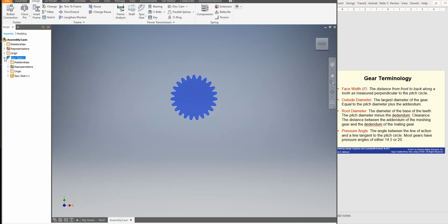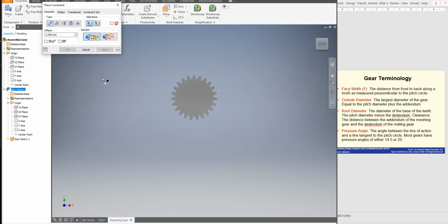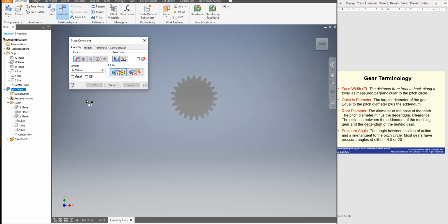At the beginning, let me say that we have the origin of the file and we have the gear origin. Let me say that I want to go to assembly. If you remember, from the assembly, I have to say make a constraint, choose a constraint. As example, I want to mate. Let me show you what I will do. I was thinking to do the following.